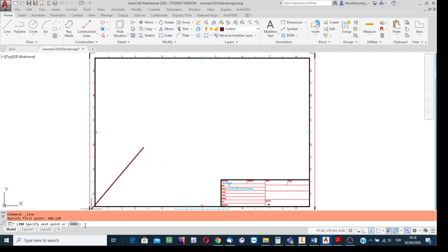Well, need to write the angle into the comment bar. But in doing this, be careful. If there is no arc simulation, then see whether the line is downwardly inclined or upwardly inclined, relative to a horizontal reference line; imagine that it is passing through the starting point of the line. If the line to create is inclined in the down direction, then write the angle as negative. But if the line to create is to be upwardly inclined, then write the angle as positive.